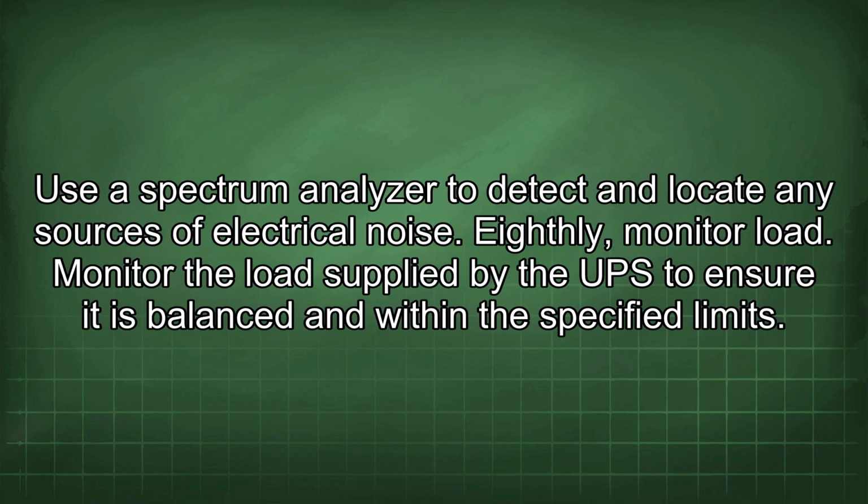Seventhly, inspect electrical noise. Use a spectrum analyzer to detect and locate any sources of electrical noise. Eighthly, monitor load. Monitor the load supplied by the UPS to ensure it is balanced and within the specified limits.